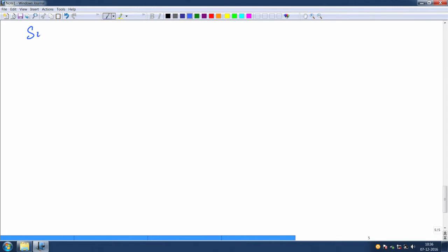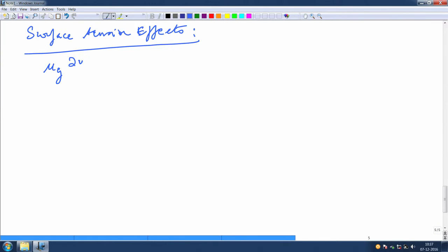Now, let us look at the surface tension effect also. Remember, we said that the surface tension effects are negligible because there is no variation of temperature across the interface, but some people have included the effect of surface tension. If you recall your initial classes, this is what happens: the stress at the gas interface is equal to mu L at the liquid side of the interface, and then there is a d sigma by dx.